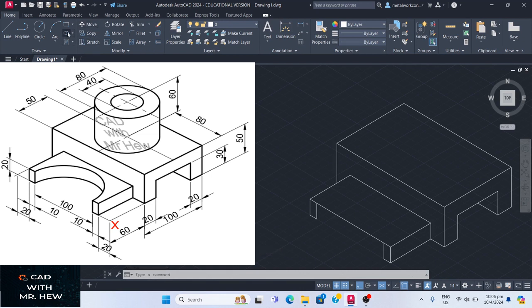All right, so we'll go again. Ellipse, isocircle, click there, specify the radius, so I click there. Parameter, start angle, parameter, angle, which is from here to there. Enter. All right. Now we can delete this line because this was a construction line that we used.